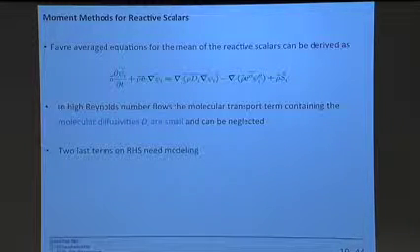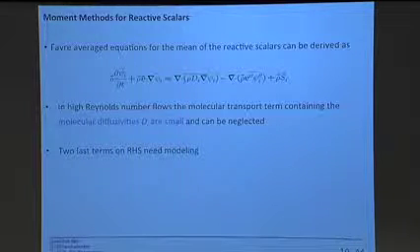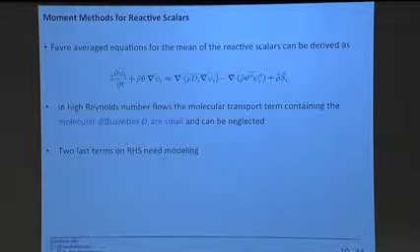This term is now the average of, we said, temperature squared, or fuel times oxidizer times exponential minus E over RT. Introduce your decomposition there, and you get very, very complicated correlations, which we need to model, or we don't know a priori how to model this. Do you have a question?